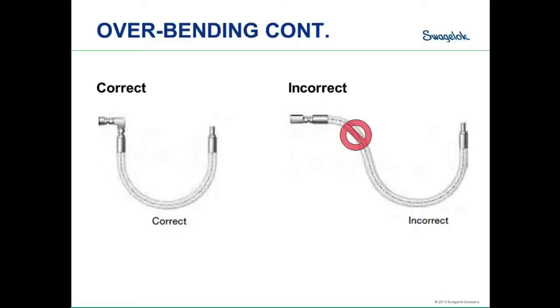And again, just to go back to my garden hose analogy, think about the spigot for your garden hoses. The spigots typically come off either right down to the ground, or they come out on a 45-degree angle. The purpose of that is to alleviate that stress that would be built up if it came right out. Additionally, you notice on most hoses they have a bend protector near that transition from the fitting to the hose. That's also to help in these types of installations.